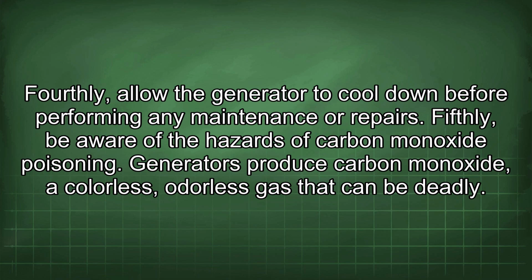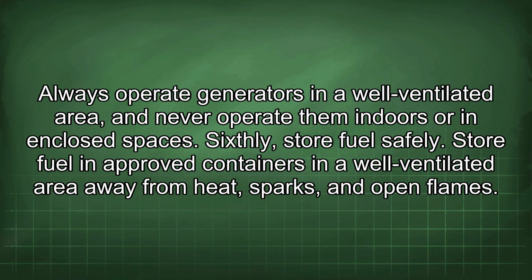Fifthly, be aware of the hazards of carbon monoxide poisoning. Generators produce carbon monoxide, a colorless, odorless gas that can be deadly. Always operate generators in a well-ventilated area, and never operate them indoors or in enclosed spaces. Sixthly, store fuel safely. Store fuel in approved containers in a well-ventilated area away from heat, sparks, and open flames.